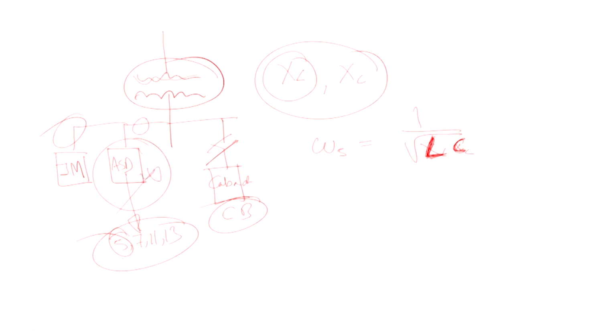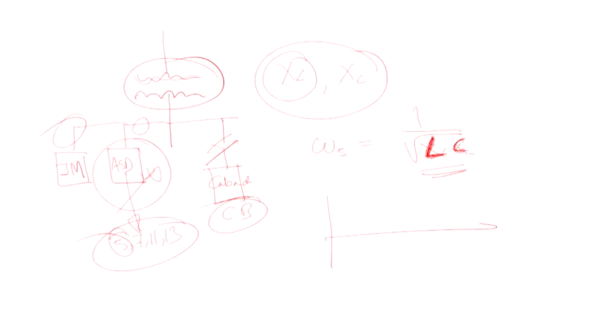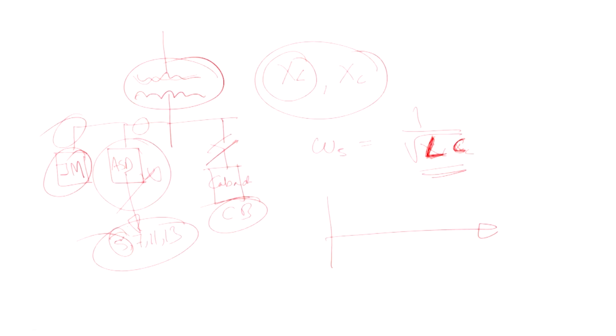This entity will have a 5th harmonic and it will cause a 5th harmonic resonance. If 5th harmonic resonance occurs, please understand that the 5th harmonic is a negative sequence, because if you are sitting on the 6th harmonic, that is co-phasor, then the 5th harmonic is rotating clockwise with respect to you. Thus, due to the resonance, this 5th harmonic value will aggravate, and this will go to the machine.